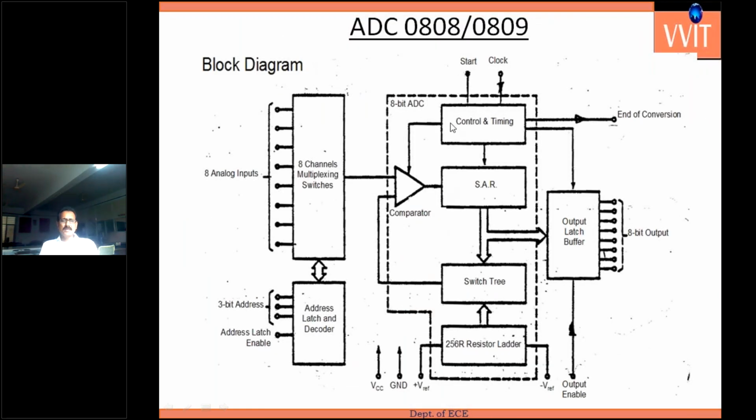Next, ADC, analog to digital conversion. This is indicated for the successive approximation register. This is the input. These are the analog inputs, whatever may be your sequence. There are 8 channels connected individually. You select any one of the channels depending on the control word. That channel's strength is compared to the predefined successive approximation voltage. If it is equal, the corresponding bit pattern is sent to the output. Now these bit patterns, with the help of the resistor ladder circuit, are generated as the voltage signal.